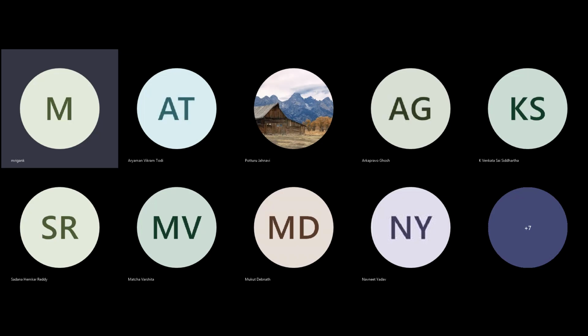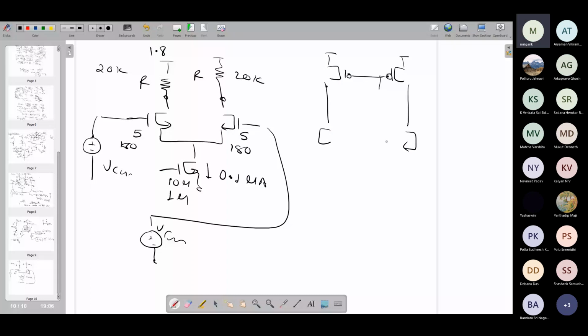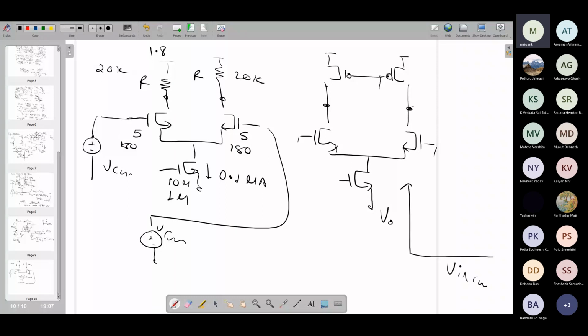Common mode issue, the gain biasing, the output biasing issue. So here also, if you do the same thing, VCM, you can see what is happening to the output node, and then you can plot this simple curve, what is happening to the V out, because both are the same. They are ultimately a common mode operation, V in CM and V out CM. Whatever curve we have discussed, you can plot and try to see what curve comes, how steep it is, etc. You can look at that.